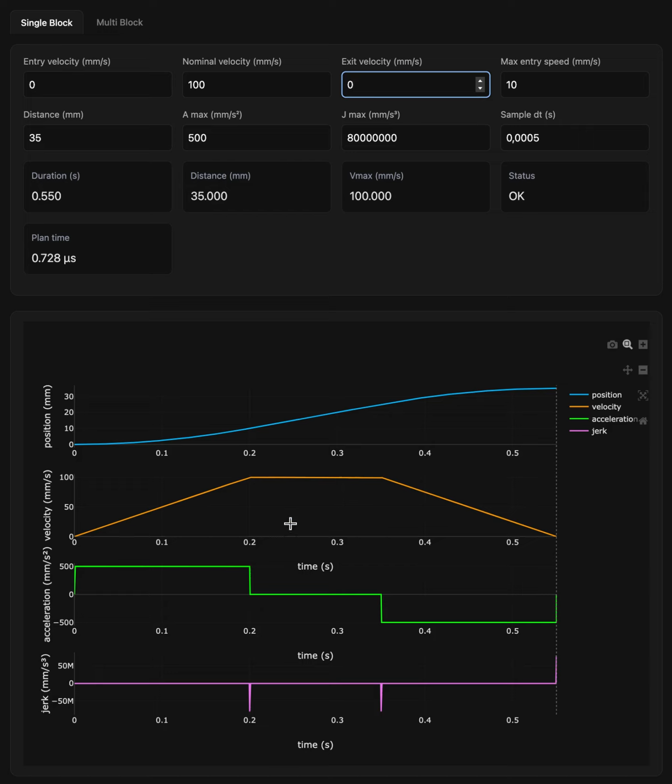The issue this has is that acceleration is a discontinuous function. You can see it here, the staircase. And this discontinuous acceleration curve causes two issues. One is resonances. This tends to excite resonances in the 3D printer. And the other one is linear advance.